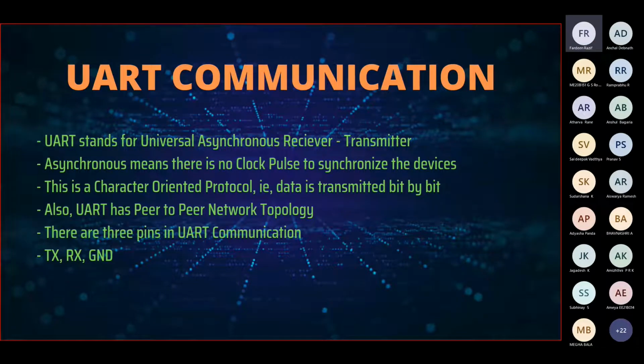And also in UART communication, the pin connections are very easy. You only have 3 pins, which are TX, RX, and ground. I'll explain what this means in a few minutes. So this is just the small intro to UART, which I wanted to tell. And yeah, so moving on.